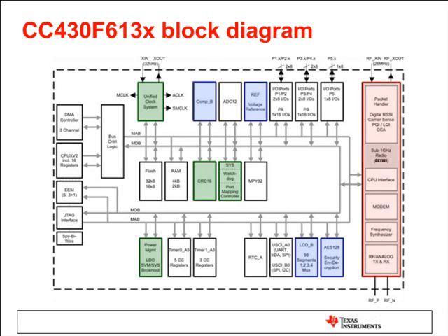Power management, the 5XX core does depend on an internal LDO that has been integrated. So the core is actually separate from the external peripherals, and that means we have the internal LDO. The cool thing about that is that we also built into that SVS protection, so you've got built-in SVS protection for very low power. You can have SVS protection for, I believe, like 200 nanoamps. And there's a higher power mode if you want faster response time for your SVS. You have the option, but you can have SVS protection for 200 nanoamps, which I think is a great achievement.